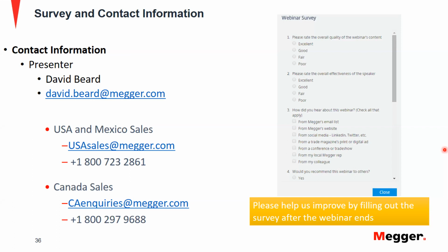So for example, if a 51P and a 51G element are both sitting on the same output contact, usually the 51P element would have a higher setting because it's related with the phase side of the system, whereas the 51G would have like a lower setting.